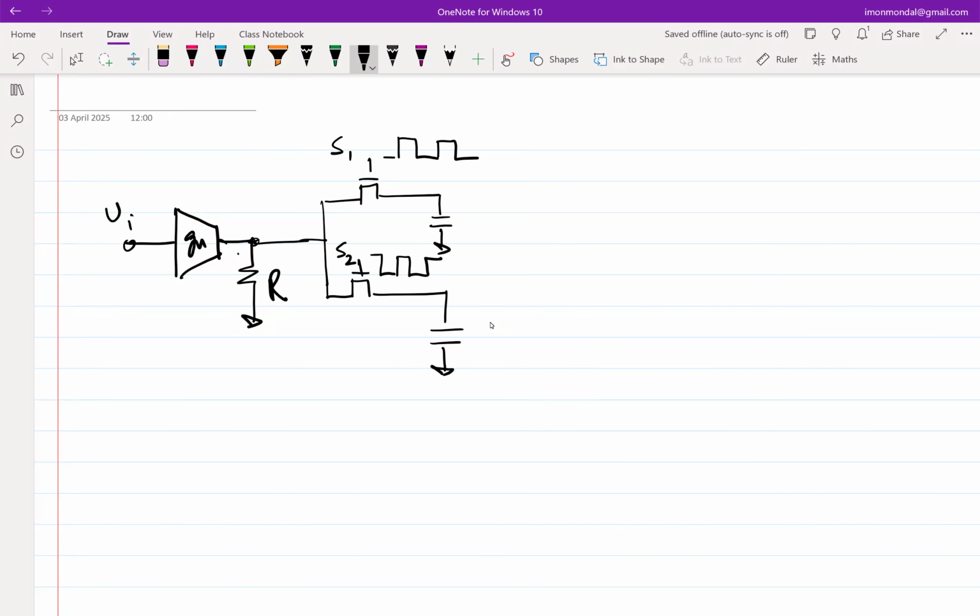So the issue with this is, whoever had made this mistake, I had pointed it out. What is the quiescent point at this node? Quiescent voltage? It's 0, right? Because how do you find quiescent? There is no input, right? So this is 0. This is obviously hard ground, 0. There is no other biasing anywhere, right? So this will naturally be 0.